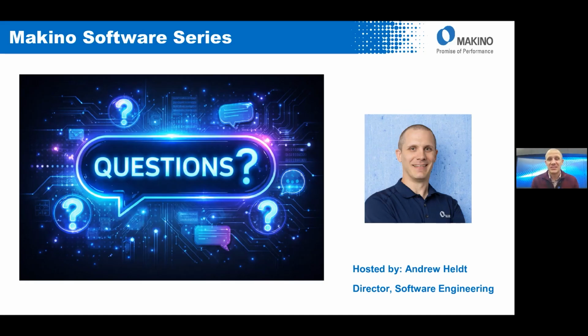So the first question is, where would data collector and data writer be installed in my shop? So data collector and data writer are deployed on a customer provided edge PC. That PC can be a physical PC or a virtual machine, giving customers flexibility to align with their existing infrastructure. Because the software runs on an edge PC, a single installation can connect to multiple Makino machines. The exact number depends on polling rates and data volume, but the architecture is designed to scale beyond a 1 machine per PC model.